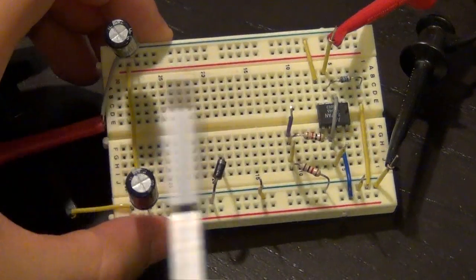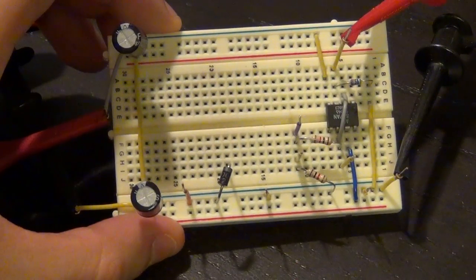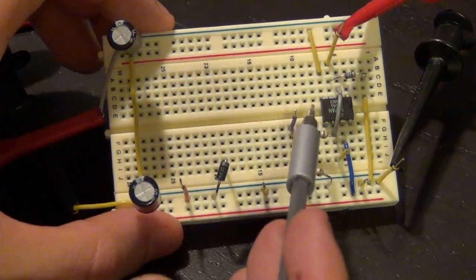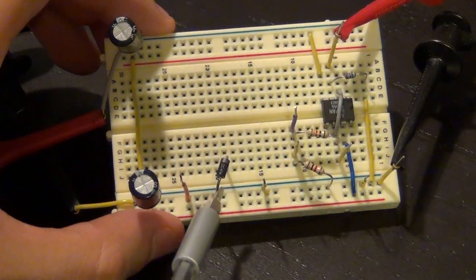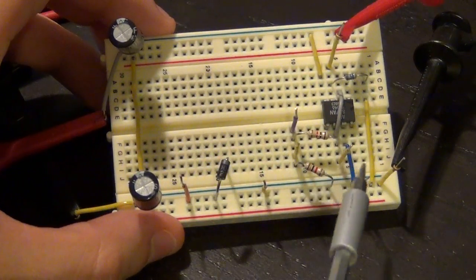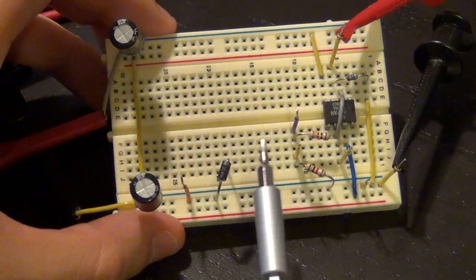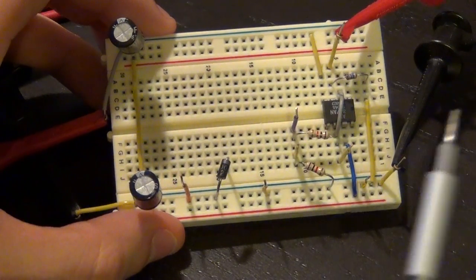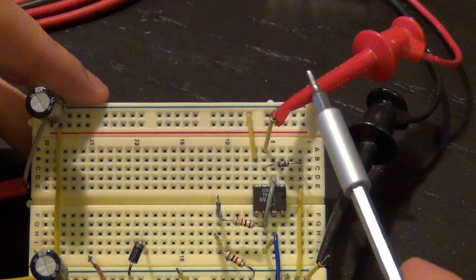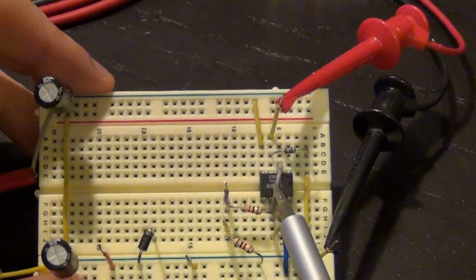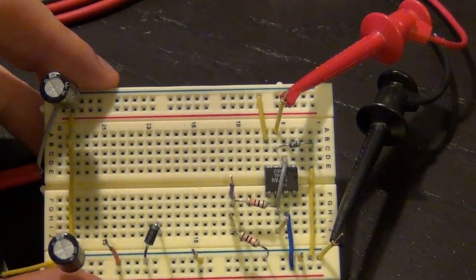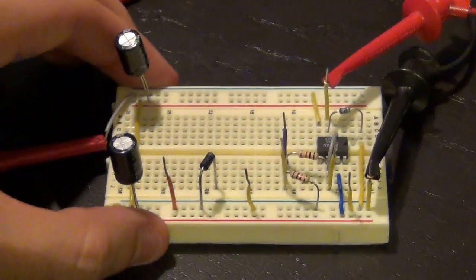As I was saying before, here's a little amplifier. It's just an op-amp in the front that's configured to have a gain of 1. And here's one of the resistor dividers, here's the other resistor divider, and here's my diode that I had drawn in the schematic. So right now the diode is not connected to the resistor divider. So I can look at the output of the resistor divider directly and put a single sinusoid input using these two connectors. So the signal comes in, goes through my little op-amp that has a gain of 1, goes through the resistor divider and comes right out. And right now it is not connected to the diode. So we can take a look and see what that looks like.